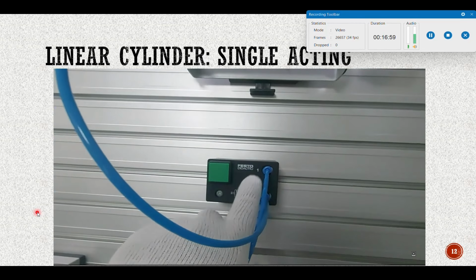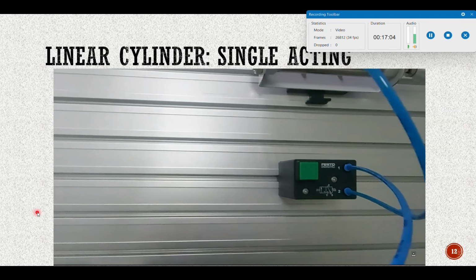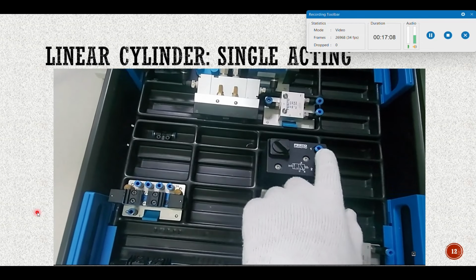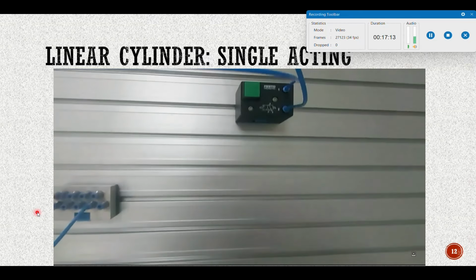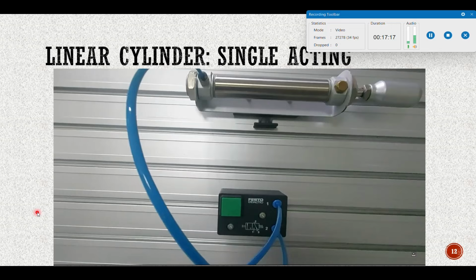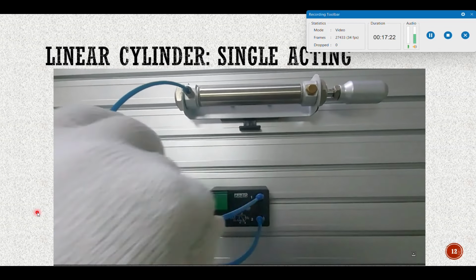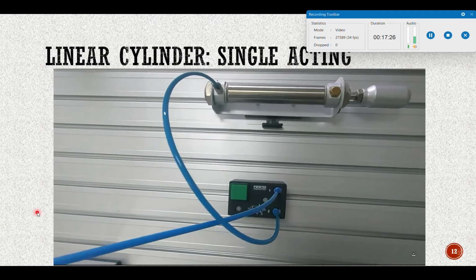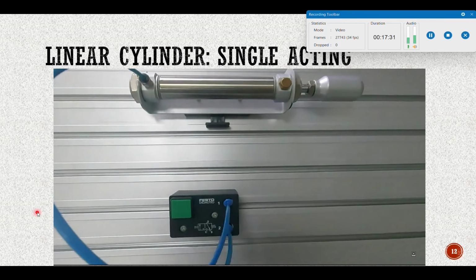So FRL is connected to the distributor and the distributor is connected to 1. Whenever you see 1, you connect it to the distributor for any valve. Like you have so many valves here, whenever you see 1, you directly connect it to the distributor, wherever it is. And the even numbers like 2, 4, 6, 8, and so on will be outputs. 1 is input, and the odd numbers 3 and 5 will be exhaust.